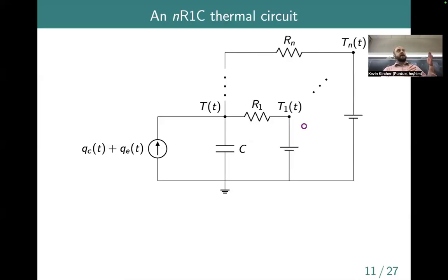So you might have one temperature node at the outside surface of a wall, another at the inside surface, and you might put a couple in the middle. So maybe there's a plywood layer and then an insulation layer or something like that. At the interface of each layer, you might put a new node. And you could again use all the rules, Ohm's law and so forth, to come up with the equations for that as well. Yes. Good question.